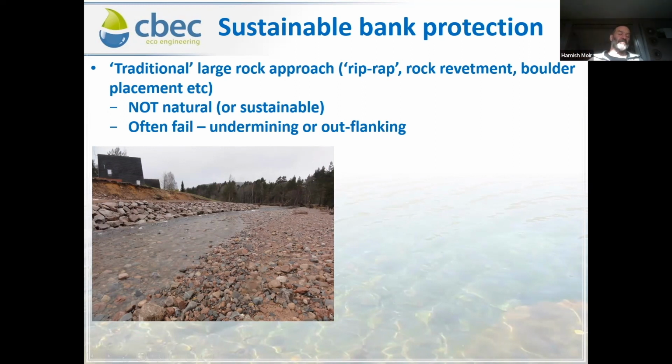Very dynamic system draining from the Cairngorm Mountains, very upland system. Where you get this type of feature, this large gravel bar developing, it's forcing the flow to the opposite bank, which is why the erosion happened in the first place. But because there's rocks in here, the river can't physically pick up that rock and move it. The energy that the river's trying to expend isn't expended by the channel migrating laterally, but it'll erode the bed vertically.